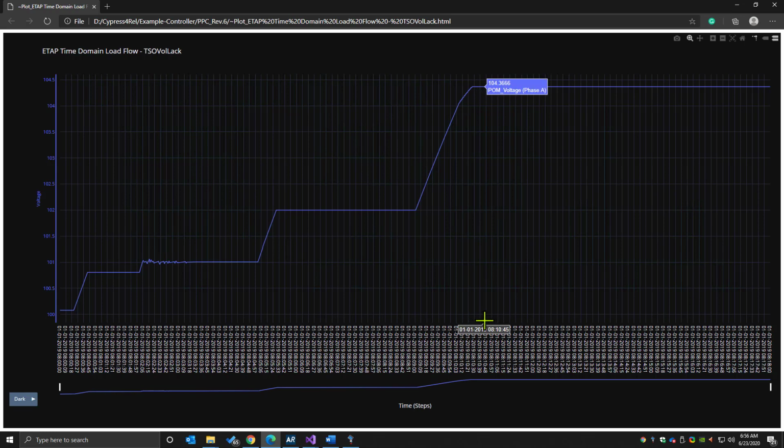it never achieved 105%. We are now limited to 104.3%, and we are unable to deliver the commanded voltage value. Now this could be because, of course, we don't have enough reactive power capability or other factors. This is, of course, for the engineering team to decide, and one of the possible solutions here is to increase the size of the reactive power compensation devices and size them appropriately to deliver the maximum amount of voltage that the TSO may ever command in that system.